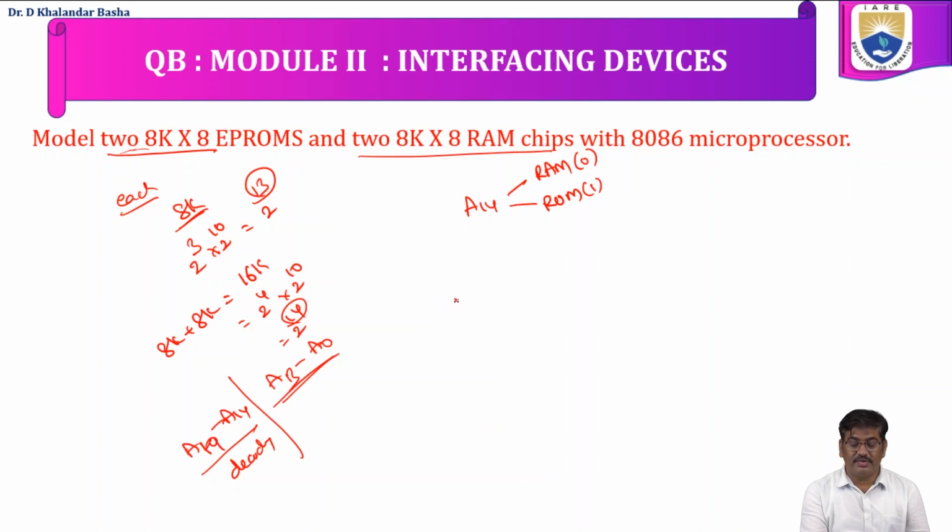At reset, the CS and IP values will be generated. The address is FFFF0H. If you observe, the higher bits indicate F, meaning all the bits are equivalent to 1. Whenever we design the interface to meet this requirement, we write the higher bits as 1. So for interfacing, first we have to generate the address mapping.